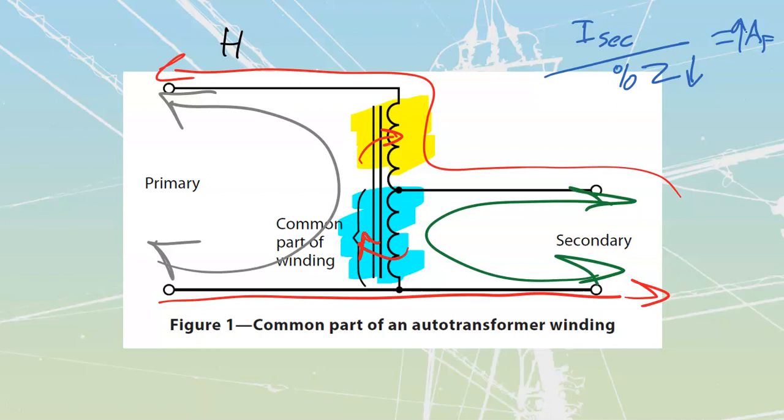Because of that, there are actually going to be some situations where they're going to put impedances ahead, line reactors and stuff like that, particularly when they're working with dangerous high voltages. The other issue is that we have common issues over here because we don't have that air gapping from one side to the other. Any weird currents, disturbances on our line, harmonics and things like that, are going to be able to get transferred all the way through to my load.